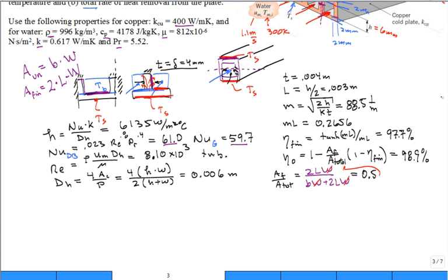So you have a resistance conceptually to go from Ts to Tb, and then a resistance to go from Tb into the fluid in the channel. And I know it's changing as we go down the length, but that resistance here is 1 over the overall efficiency of that surface times the convection coefficient times the area that the fluid sees in the channel.